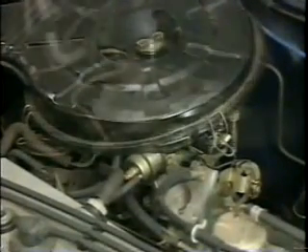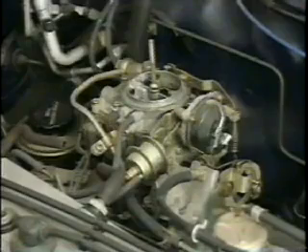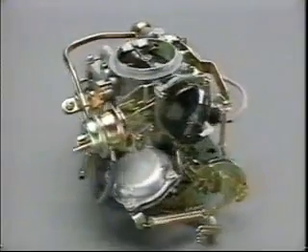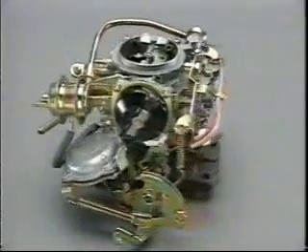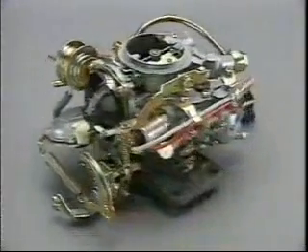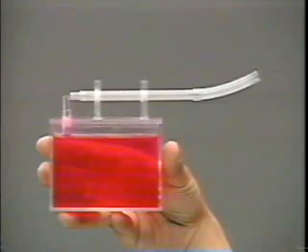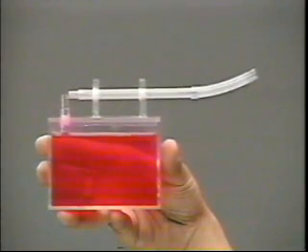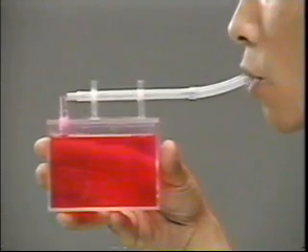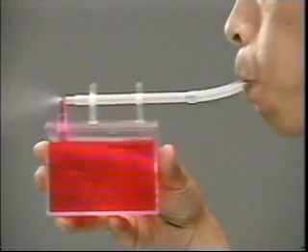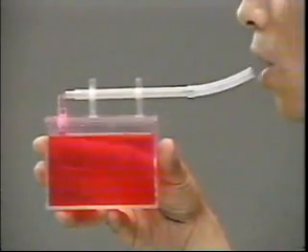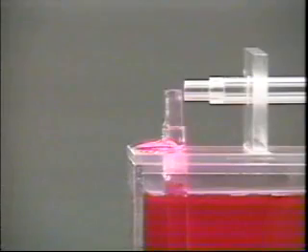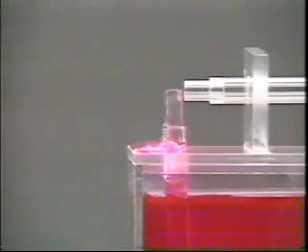The carburetor mixes the proper amount of air and fuel in accordance with the operating conditions of the engine and sends it to the combustion chamber. The principle behind this is similar to that of a manual paint sprayer. When air is blown through the pipe, the liquid inside is drawn up and mixed with the air, forming a spray. An increase in the speed of the air blown through the tube will draw up more liquid and create a mist.